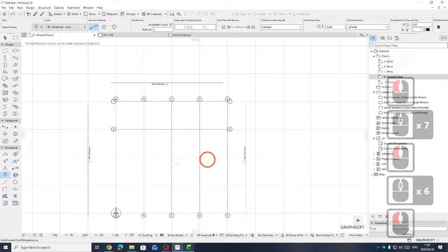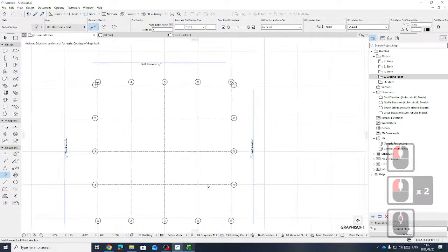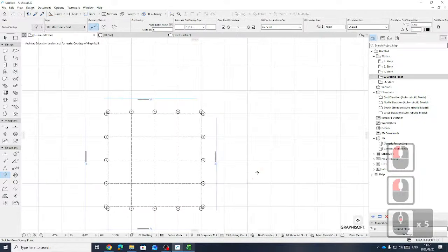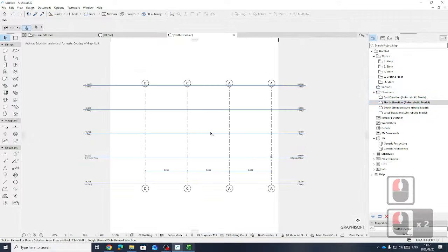Okay, so this is quite intuitive. Done. One last one. I have noticed if there is a marker in a way, it doesn't like having a marker there. You can stretch out the heads later, but for now, just get your system set up. Then if we go to any elevation, you'll start seeing the grids.